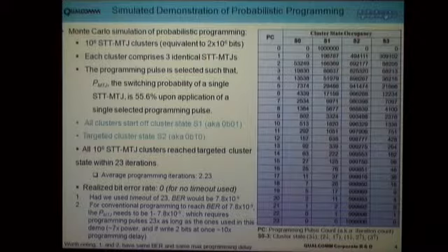require the switching probability of STT-MTJ to be very close to 1. And that requires the corresponding programming pulse to be 23 times as long as the ones we used here. And that extends to 7 times in power and 10 times in programming delay if we write 2 bits at a time for deterministic programming, just like apples to apples.